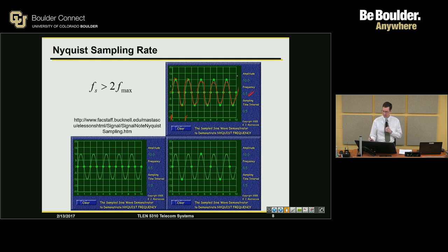Now, this would be the case where I'm sampling at every half second, which is obviously higher than twice the frequency. In this case, down here, I'm going to sample at exactly twice the frequency, is what I meant to say. So I'm going to be sampling twice on each cycle. So I do here, here, here, and here. And if I've got those sample points, I can look at that and I can say, yeah, I can generate my original signal from that.